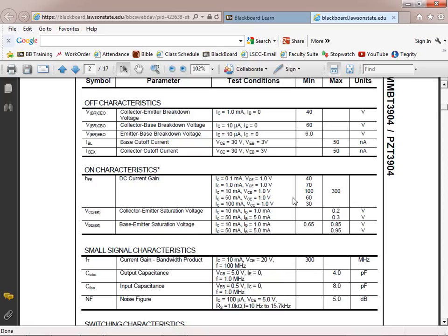But when we deal with a switch, a saturated switch, which we're going to look at later in a minute, one of the main uses of a transistor is as a switch. This is one of the reasons that they took off so fast, was that we could replace these mechanical switches with something that was electronically controlled, right? And now all of a sudden I can turn things on and turn things off with very little current, right? I can come over here and hit a little button on my cell phone and turn on my cell phone, right? With a saturated switch, right? You understand that?